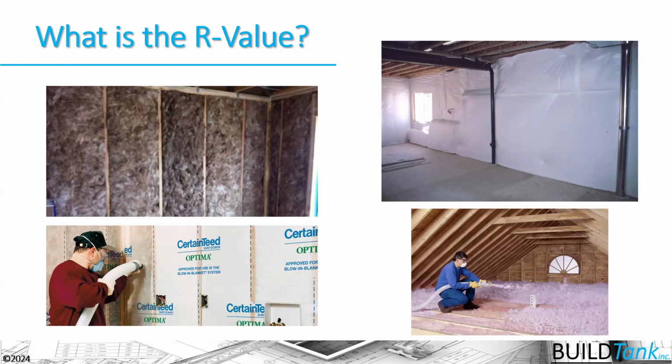If we're using the prescriptive approach, it's got to be like R20 plus 5, or an R30 cavity without anything on the outside. If they're using a performance compliance approach, they might be able to trade off, and potentially they could have an R19 in that cavity. But if they did put an R19 bat in that cavity, remember, it's not performing like an R19 bat, even if it's installed properly. So they should be modeling it as an R18 in that cavity.